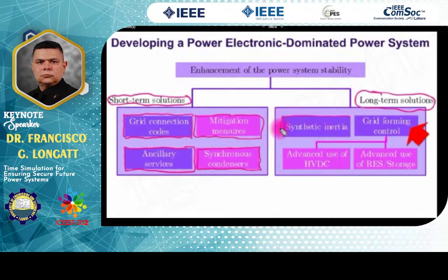Many countries around the world have been looking to enable primary frequency response in power converters. Primary frequency response can be enabled on them. However, what is very important that you must understand is that the power converter has no overload capacity. It's not similar to the synchronous machine.